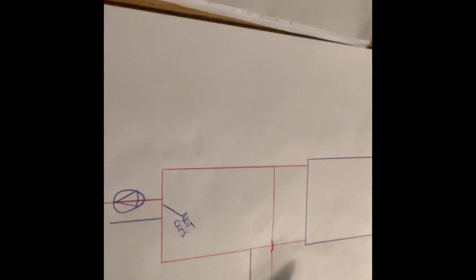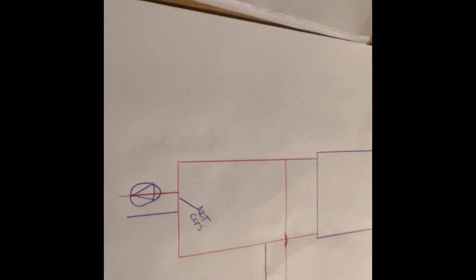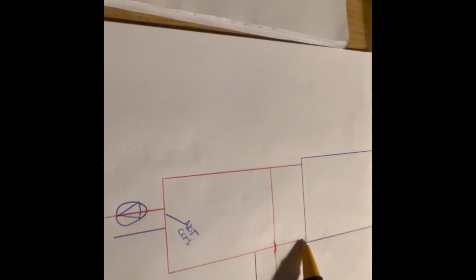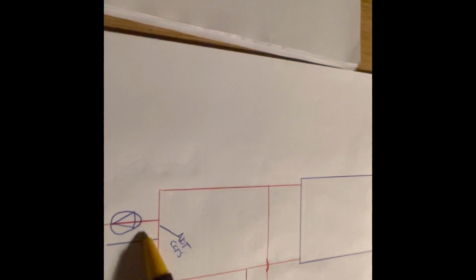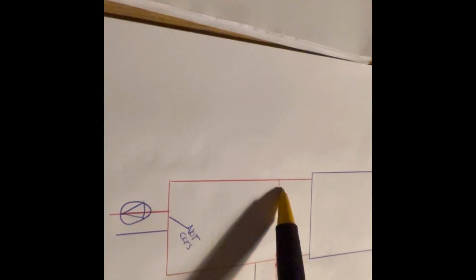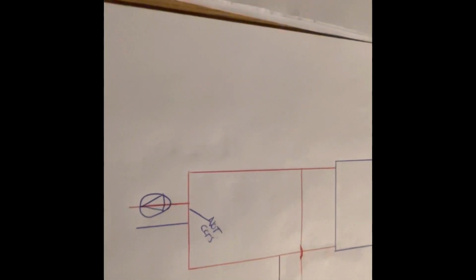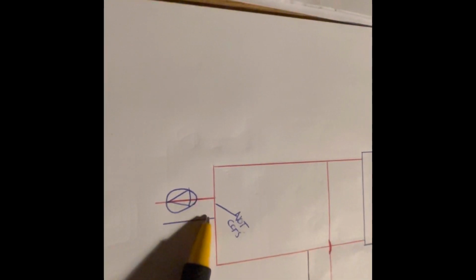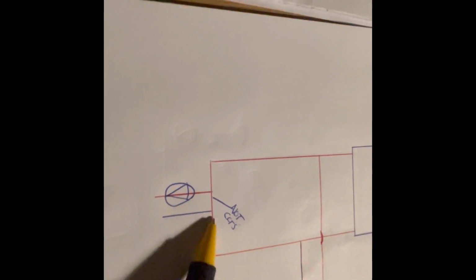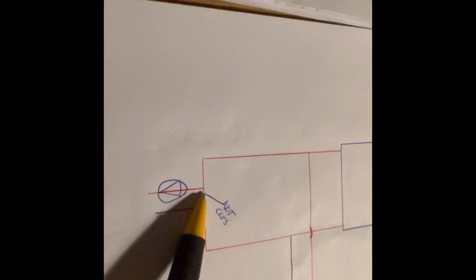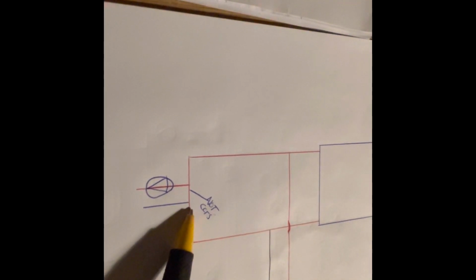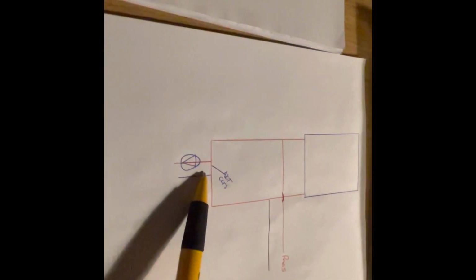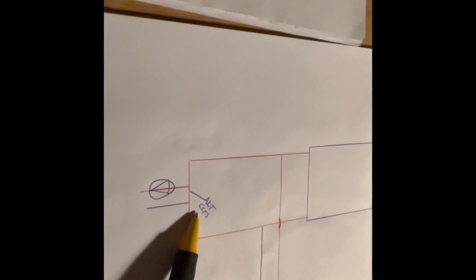So a little sketch on what Andrew and Adam are constantly on about is, what you see is people create a primary loop there and they run the radiator circuit off the primary loop, and then they run the underfloor heating circuit off some close couple T's there. Those are not actually close couple T's the way it's been done. You're creating a bypass, and water will always take the route of least resistance.